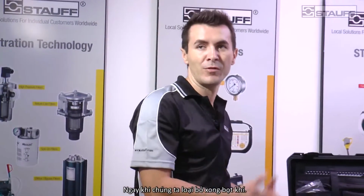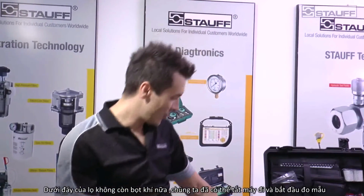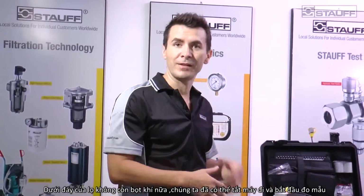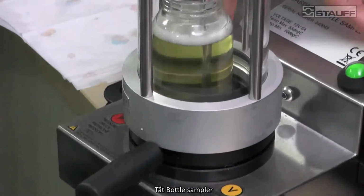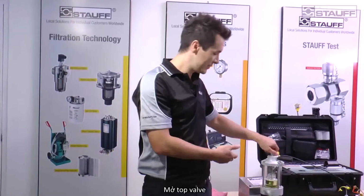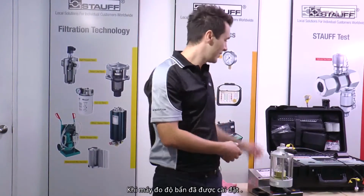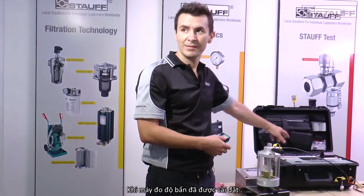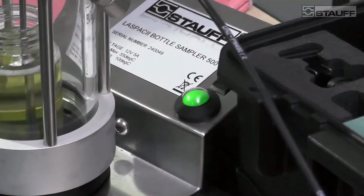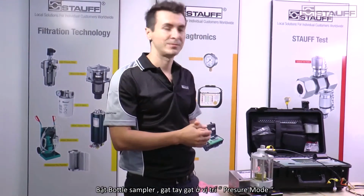Once we finish removing all the air bubbles, so there's no more bubbles down the bottom, so now we are ready to turn it off and then commence the test. So we turn the bottle sampler off, open up the top valve, change the handle to pressure mode. When the machine is already set, so make sure the machine is turned on, and then start the bottle sampler in the pressure mode.